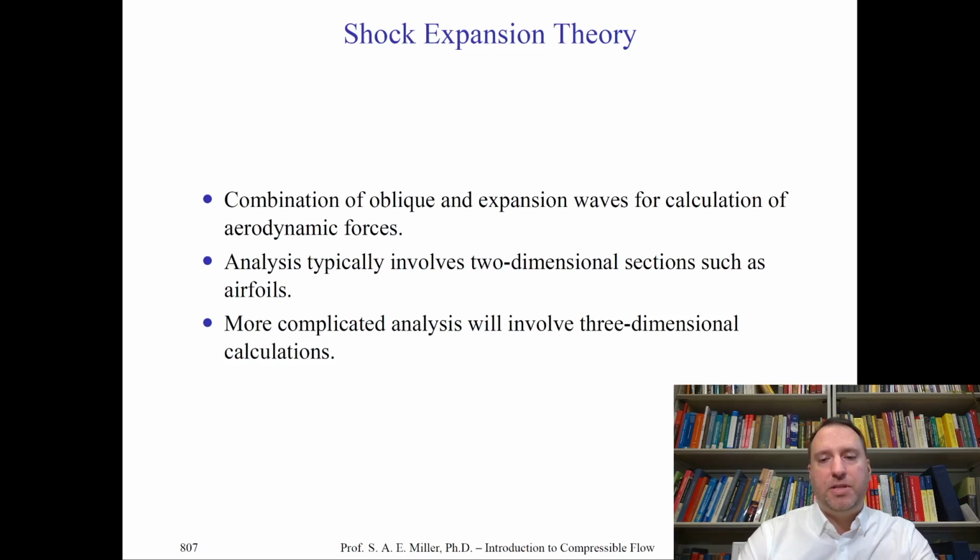And we'll show this through one particular example and example problems, but you can apply this to anything, of course. This analysis typically involves two-dimensional sections such as airfoils. Of course, this all can be done in 3 dimensions. Our example here has a unit span, meaning, say, 1 meter into the page in the z direction. Now, more complicated analysis will, of course, involve 3 dimensions, but there's nothing in our theory that's really 2-dimensional anyway. We're just applying it to, say, shocks from wedges, which are 2D and planar. We can, of course, use the conic sections and apply the same Prandtl-Meyer expansion theory in 3 dimensions.